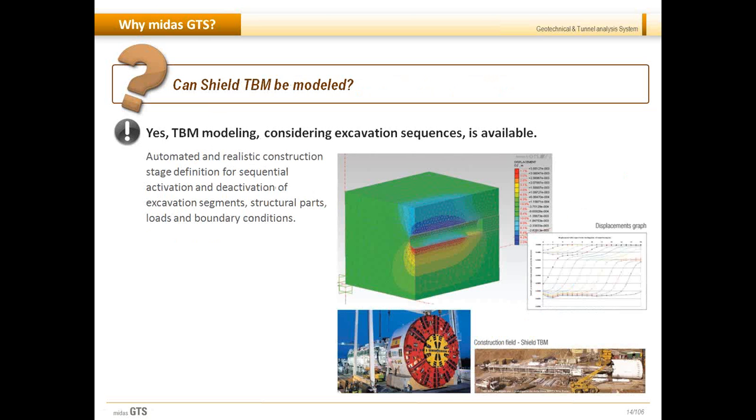Now, Shield TBM is also a big problem for some companies. In GTS, it's very powerful to do Shield TBM analysis because you can use the construction stage analysis and investigate the stage-by-stage excavation and the behavior of the soil.